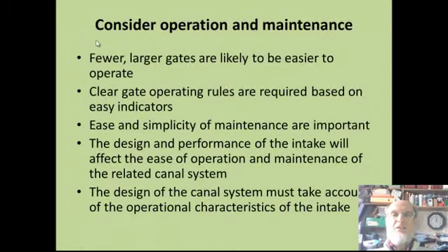We need to consider operation and maintenance early in the design process. Firstly, fewer and larger gates are likely to be easier to operate, and they're less vulnerable to blockage from trash. We need to have some clear gate operating rules, which can have some simple indicators of when gates should be operated.